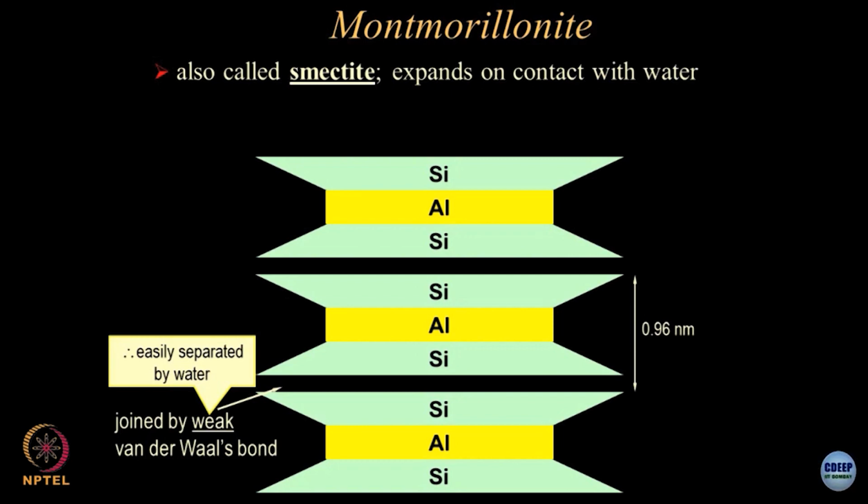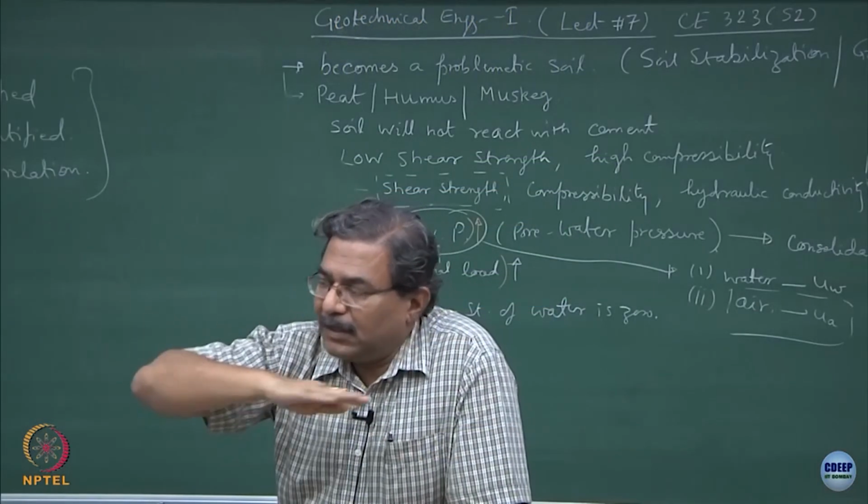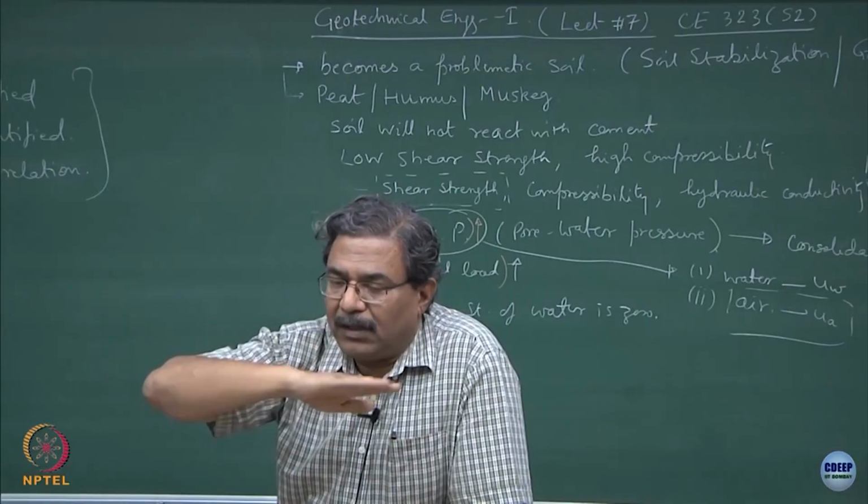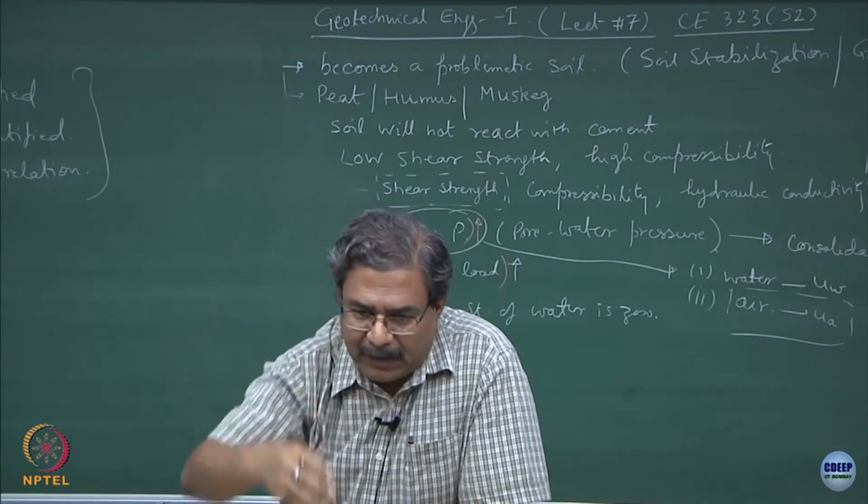But in sports, it is becoming useful because this is what is known as smectite. Smectite is one type of montmorillonite which is to be added to make pitches very stable for the required duration, alright. And then as I was giving you the logic, captains, they want to water the pitch after the first innings are over, second innings are over, and so on, and they want to roll it with a light roller, heavy rollers, all the dynamics will come into the picture.